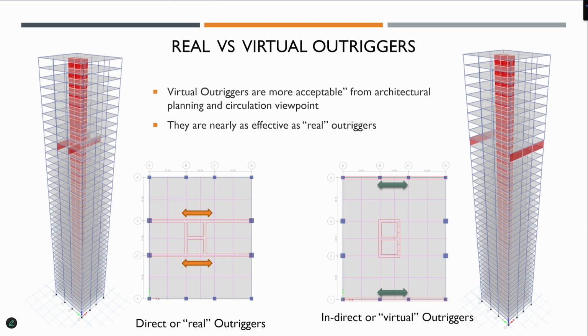So it's a box effect. You put the walls of the box on the outside, and the box still becomes rigid, wherever you put those dividers. So the two floors and this wall can be converted into a box, which is rigid. And once it becomes a rigid box, it doesn't matter where it is located.